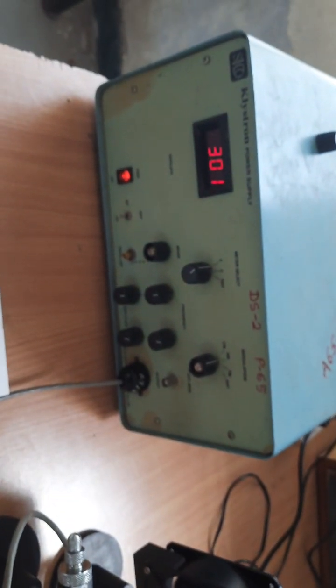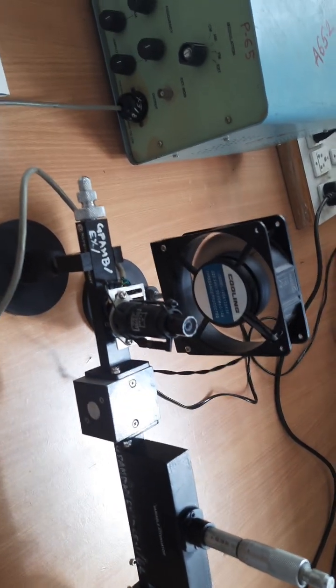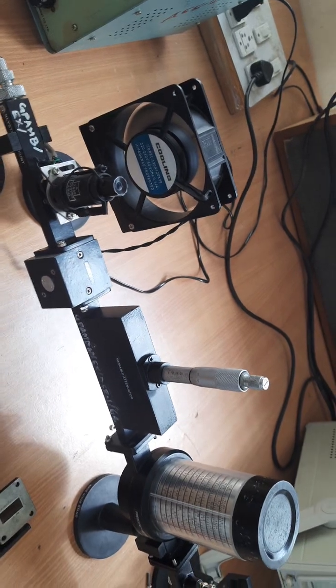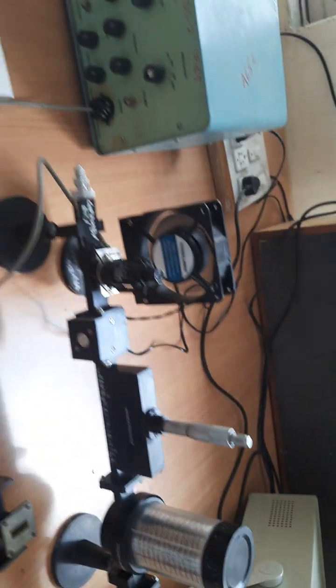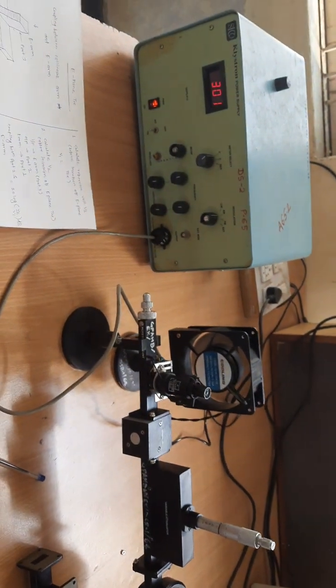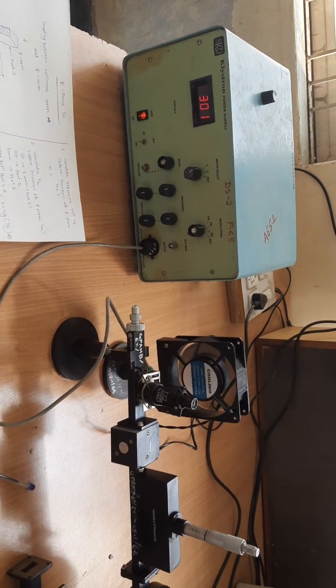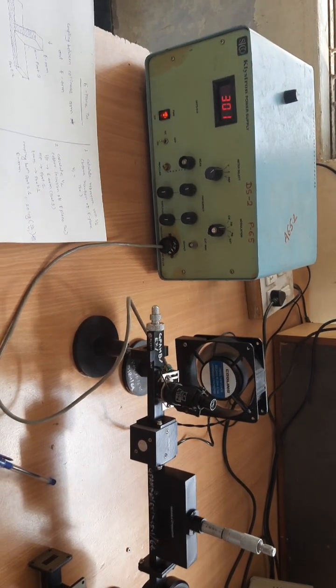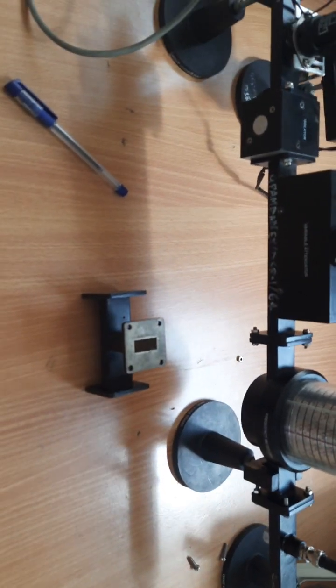This voltage is necessary to generate a response from the Klystron. With the help of 300 volt, the Klystron will respond properly, and the microwave frequencies will be generated and propagated through this microwave test bench, and we will get a square wave output. After increasing the beam voltage to 300 volt, we have to wait for 1 or 2 minutes so that your Klystron tube will respond properly, right? Meanwhile, during the waiting period, we will take a review.